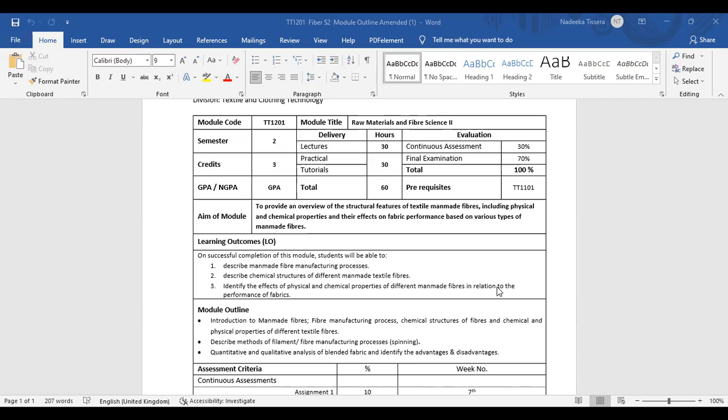If you take cotton yarn, inside it you have cotton fibers of different lengths. You subject them to opening, carding, then align them, twist them, and make the continuous yarn. So inside a cotton yarn you have short fibers. It's the same with wool fibers.